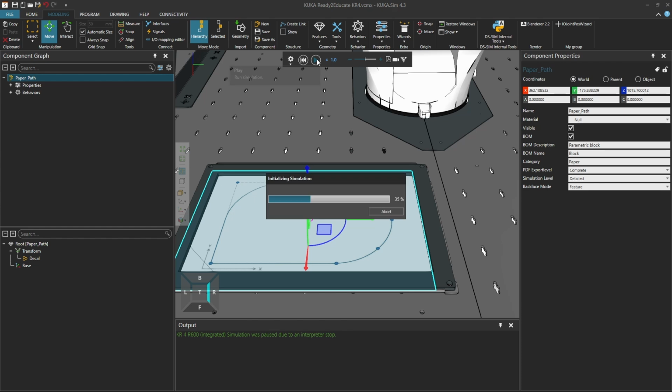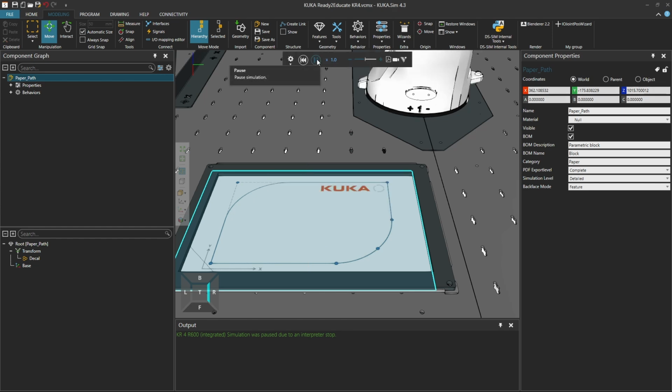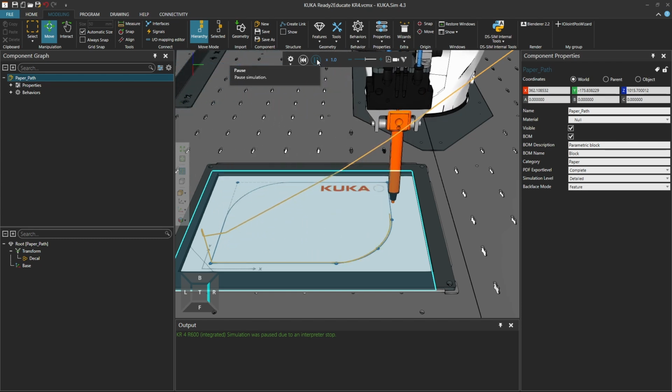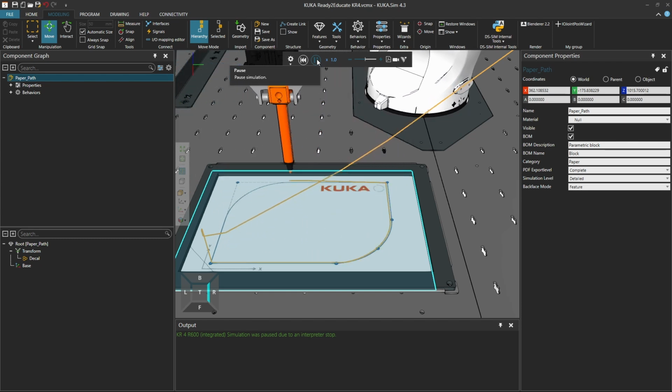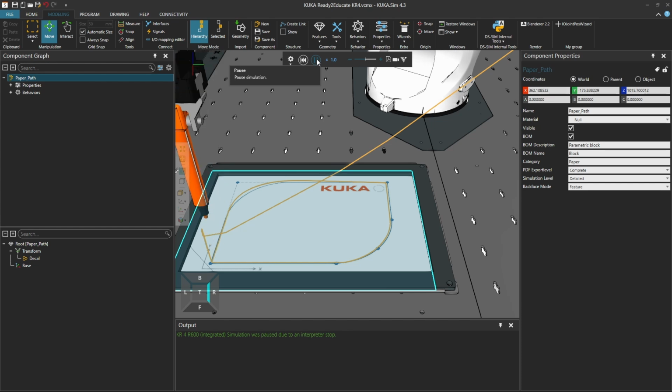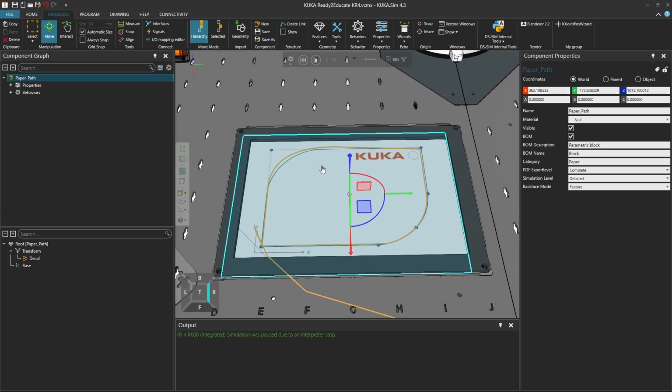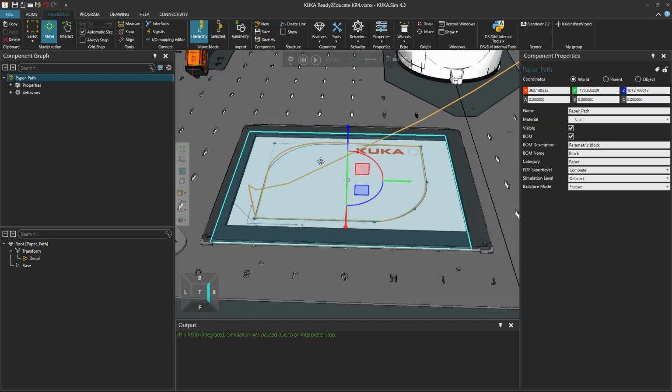And with these little adaptations, you can now change maybe your bases from KUKA.Sim to reality, or some other, how would you say, things that you imported into the simulation and that you now want to change. And you can see it fits pretty well. It's maybe not perfect, we can still tune it a little bit, but it's good enough.